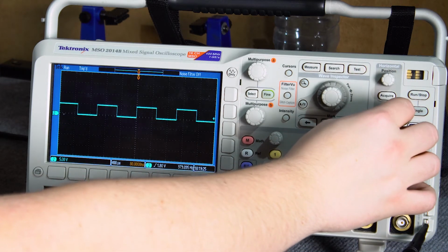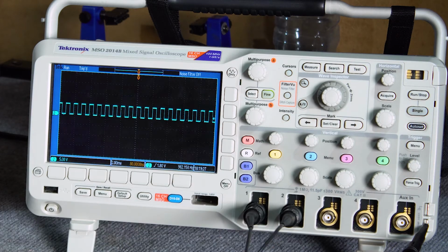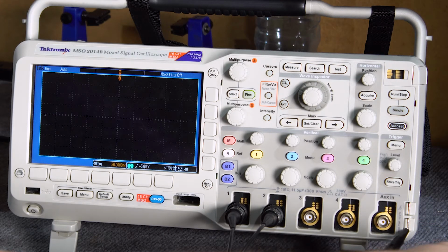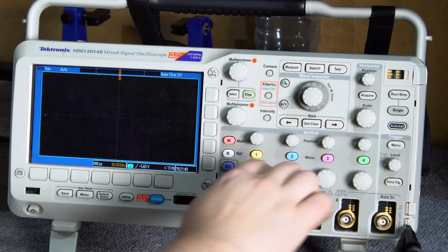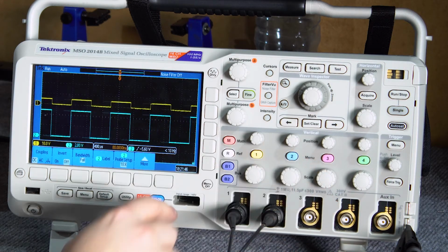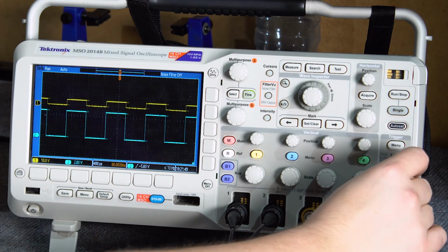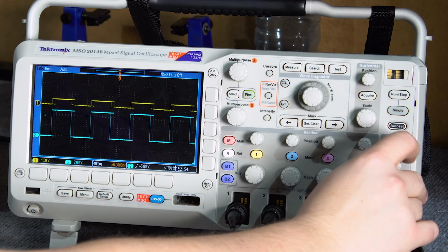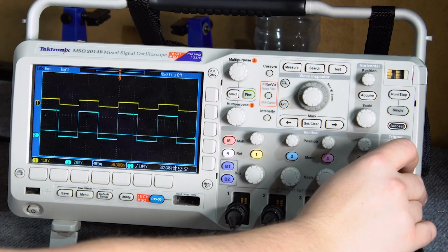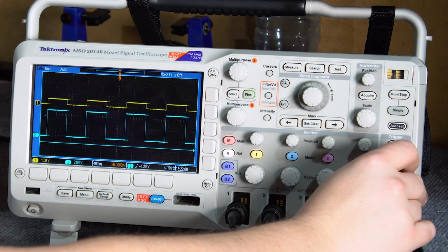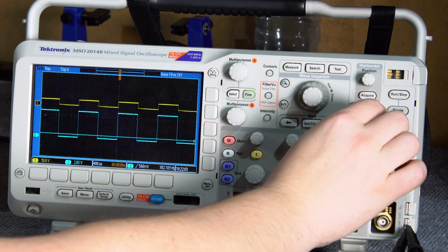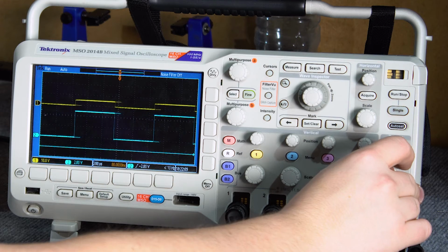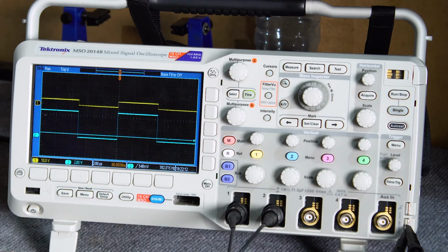This is the voltage value at which the system will start to draw the waveform from the left to the right of the screen. When you observe periodic waveforms from 2 or more channels at the same time, all of them should be stable when the triggering is set correctly. If we are dealing with non-periodic waveforms, then the picture will not be stable. Digital oscilloscopes have a built-in memory, and thanks to it they can test non-periodic, impulsive and other random events by means of triggering. When we set the triggering level appropriately and turn on the single mode, the oscilloscope will snap the image until the user decides that he has analyzed the waveform.